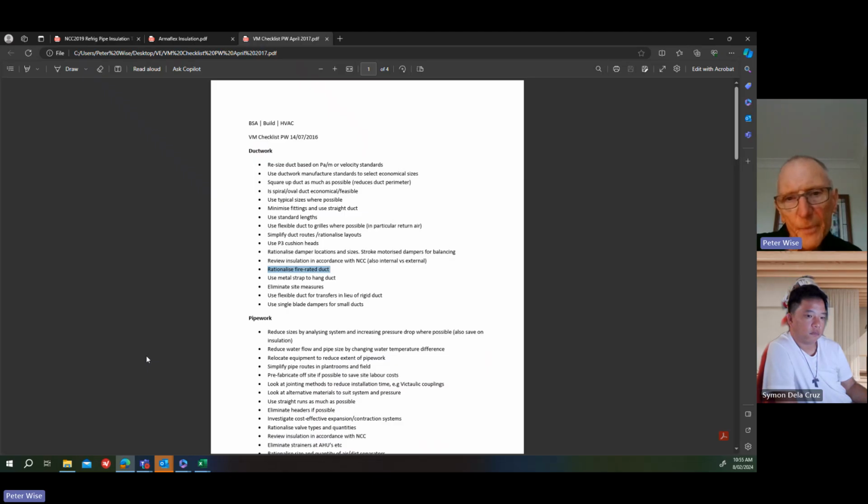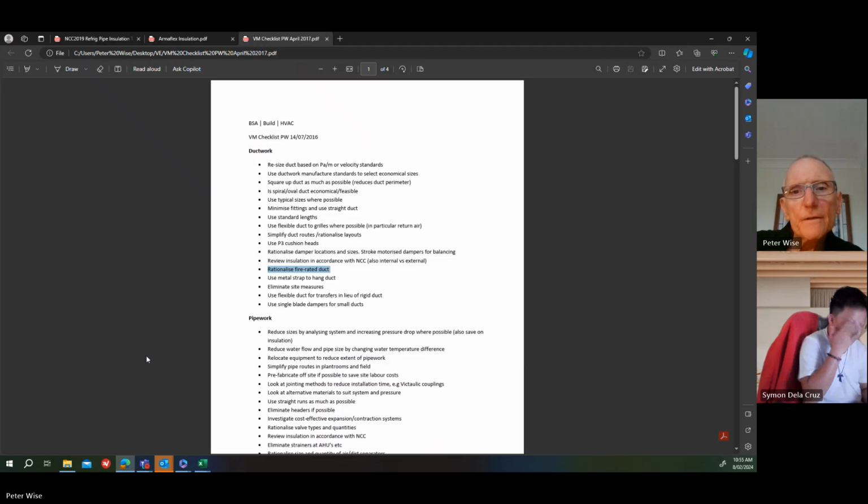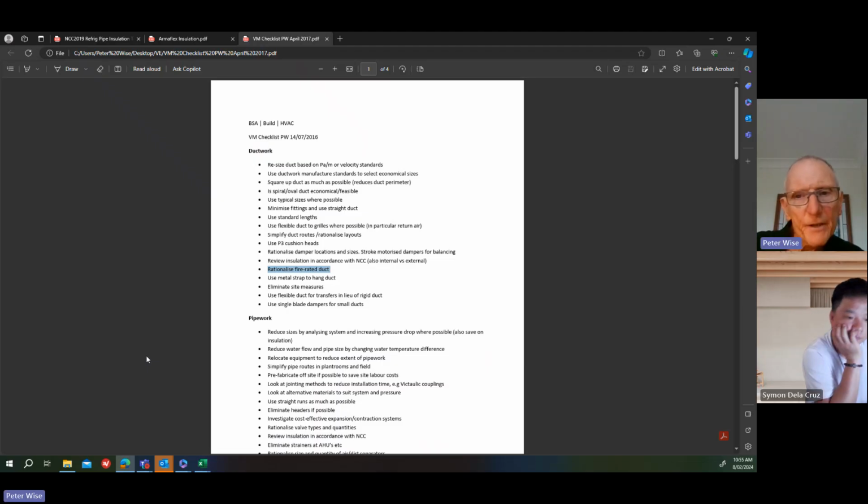But anything outside the pump room, so the air coming in from outside, if it's ducted in, has to be fire rated, because you can't use fire dampers, because if a fire damper closes, you've got no ventilation. So that duct has to be fire rated so that you've got a guarantee that the air coming in won't be stopped.